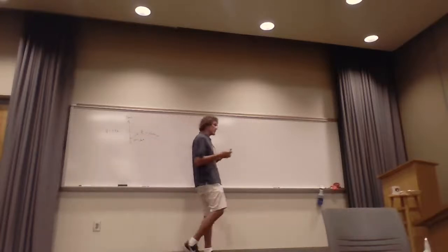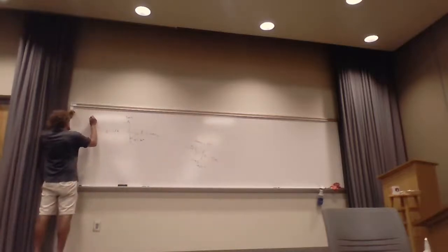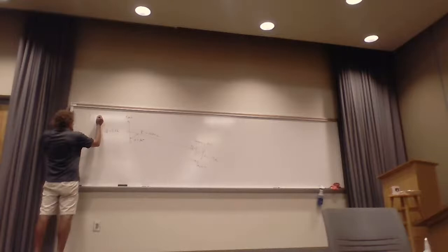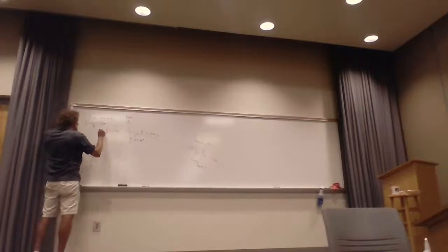This is a straightforward thing. First, let's see, the wavelength or the frequency was what? 10 to the 8 hertz? Yes. Oh, yes. 100 megahertz, right? Yeah. Yes. That's 10 to the 8. So that means the wavelength is C over F, right? And that will be 3 meters, correct?